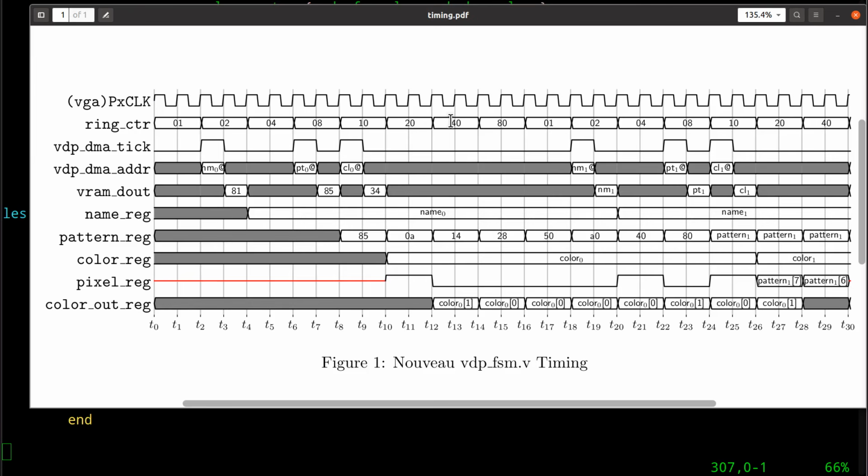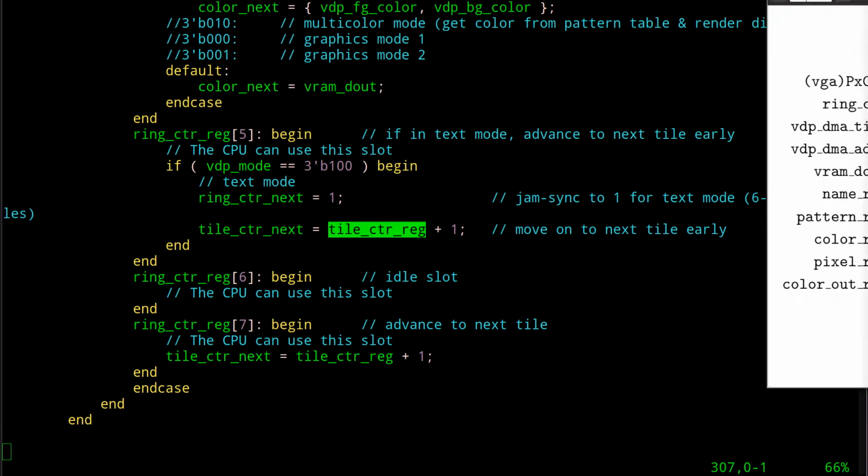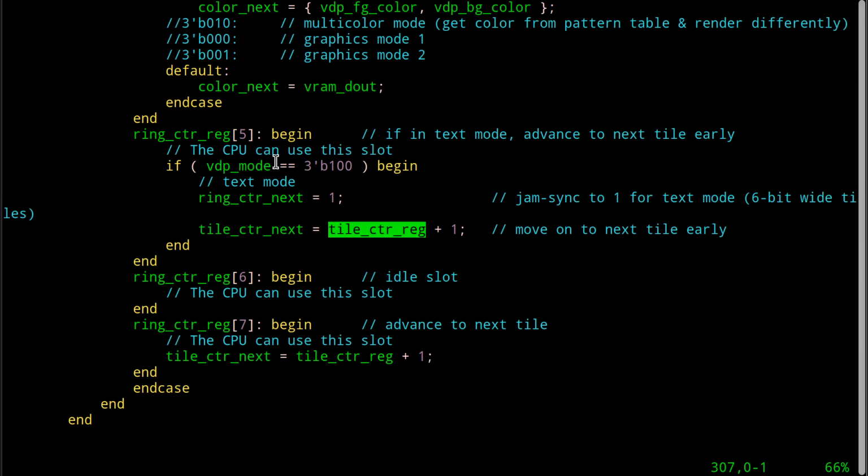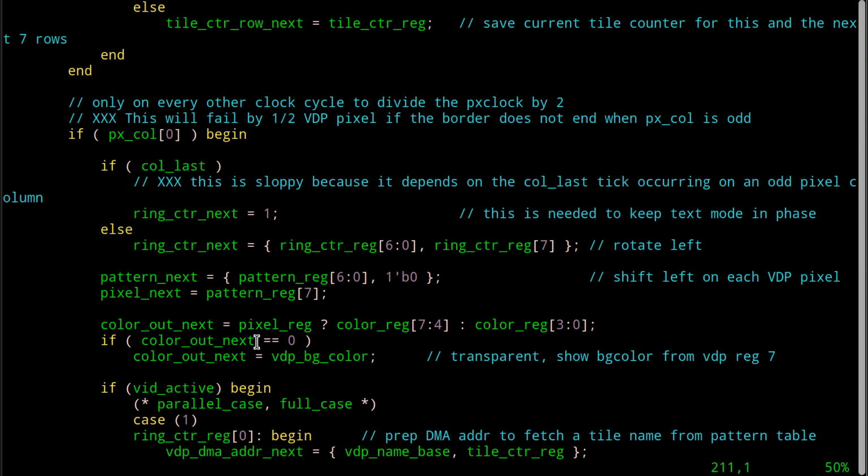That's why we're going by 6s when we're in text mode, or we're going to run all the way to 8 in the graphics mode. So if this doesn't happen and I'm not in that mode, I don't do anything at all. And I fall into here and I don't do anything at all. And then I fall down here. And then down here is when I finally advance myself to the next tile, which is the next character tile on the current row. And then I simply fall through and wait for the next clock to update my state again. That's the whole thing.